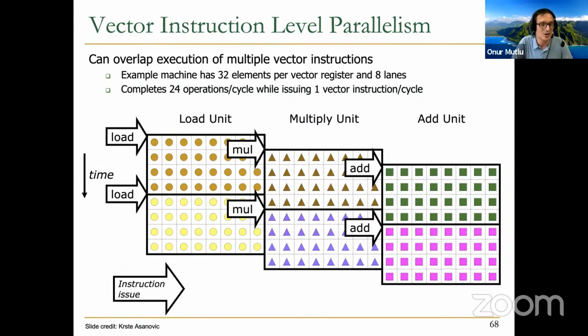Okay, but I will leave you with this picture. Basically, this picture shows essentially what an array plus vector processor executes, just to harp on it, because we've seen it multiple times. But this makes it concrete again. In this example machine, you can have 32 elements per vector and 8 lanes. And basically, each load takes 4 cycles, because 8 elements are executed concurrently in the same cycle, as you can see.